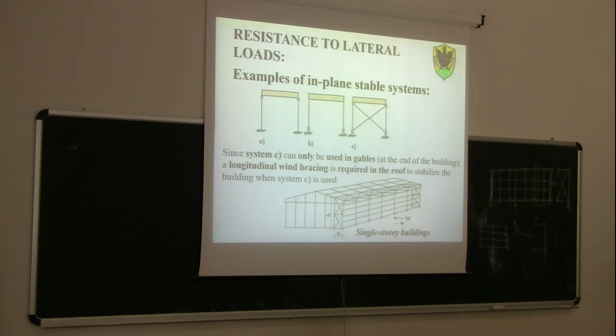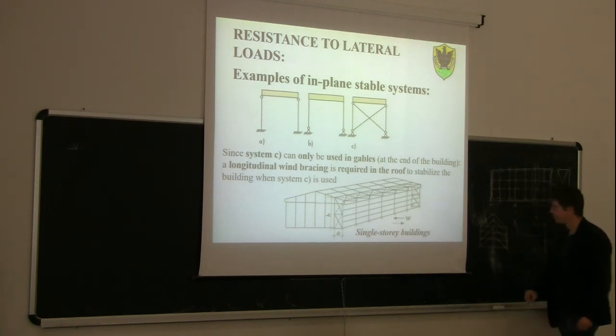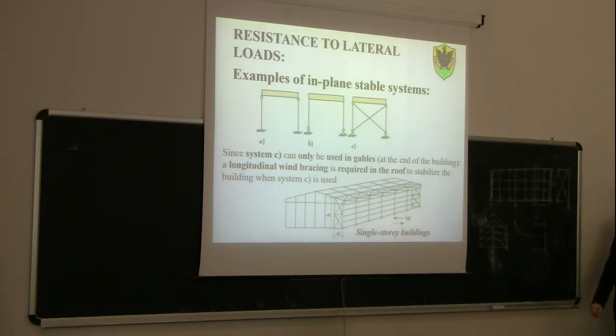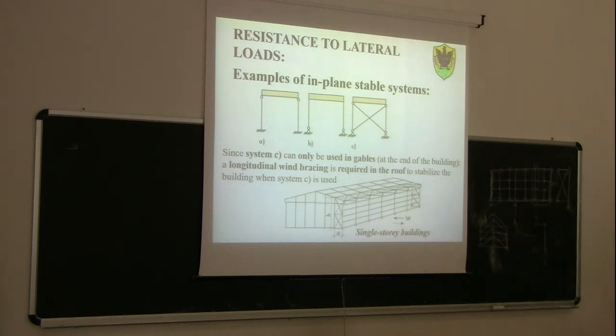So? I would have something like this. So the system will be clearly unstable. Okay? Even if the purlins are very rigid. Why will it be unstable? Because the purlin is very rigid, but the connection between the purlin and the frame is weak. So the system is unstable.